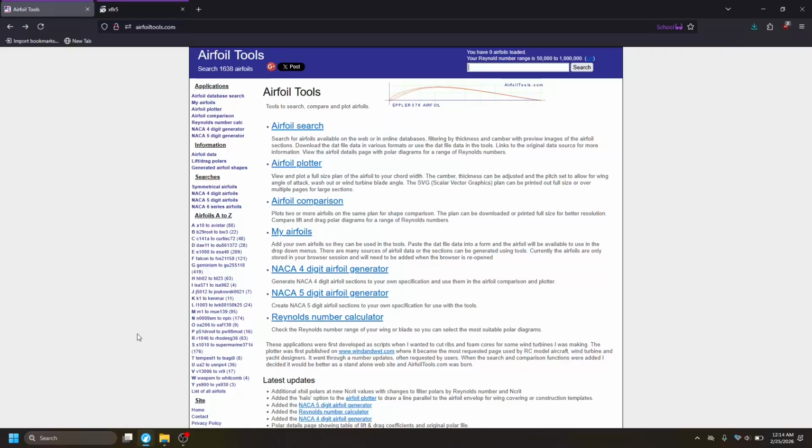I'm here to explain and go through some of the basics of STAR-CCM, which is a CFD software that can help us analyze our design and iterate and make a better aerodynamics package for our car. In this very first video, we are just going to be going over how to pull an airfoil profile from the internet so that we can then go and put that into STAR and do a 2D simulation.